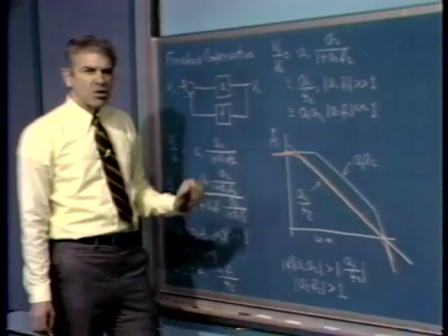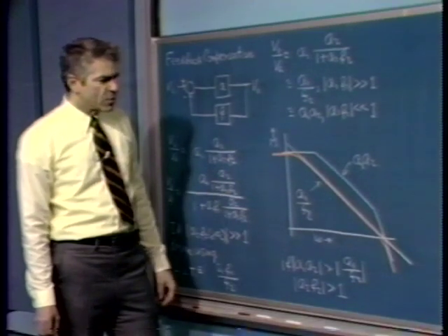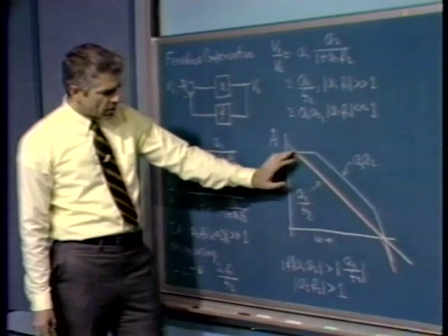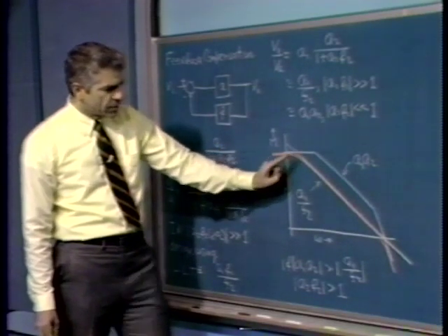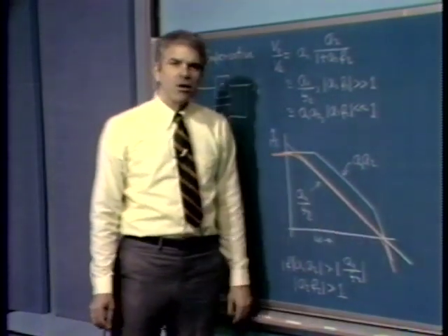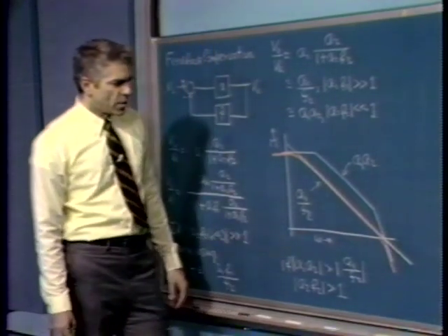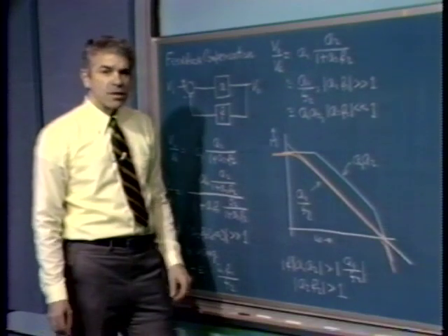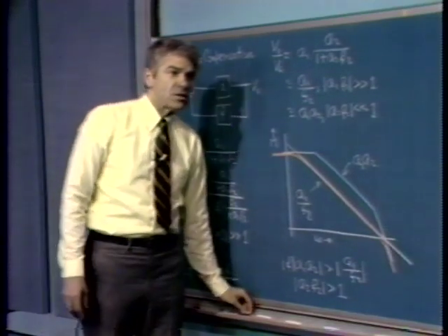We'll very rapidly relax this and make an even cruder approximation and really not worry too much about exactly what goes on in this vicinity and this vicinity. Simply go blindly ahead and take the lower of the two curves at all frequencies. We find that very frequently gives us completely satisfactory information for use as a design tool.